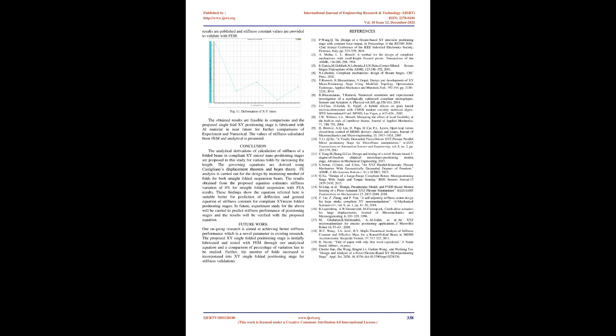Conclusion. The analytical derivations for calculation of the stiffness of a folded beam in compliant XY micro/nano positioning stages are proposed in this study for various folds by increasing the length. The governing equations are derived using Castigliano's displacement theorem and beam theory. FE analysis is carried out for the design by increasing the number of folds for the straight folded suspension beam. The results obtained from the proposed equation estimate a stiffness variation of 8% for the straight folded suspension compared with FEA results.